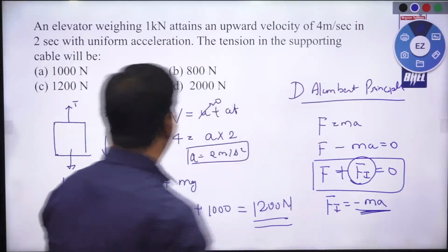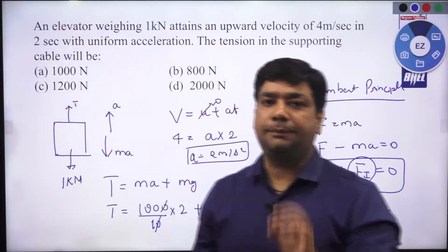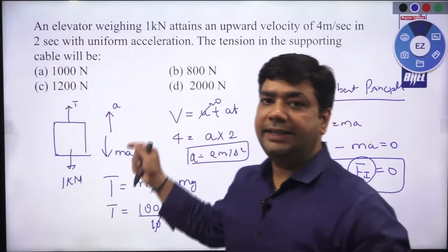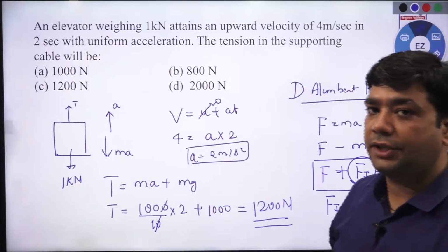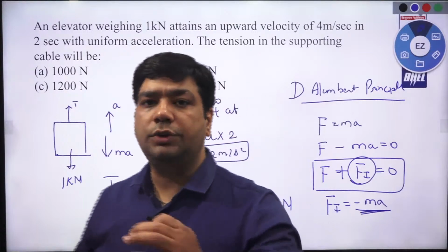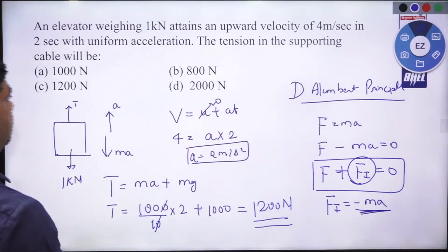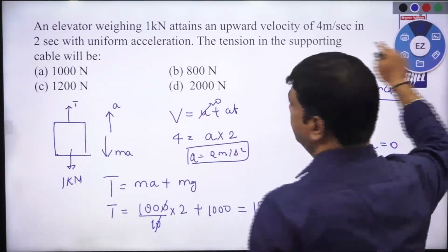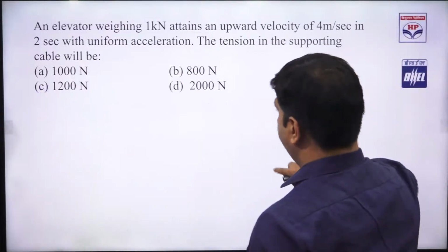So the moral of the question is that you understand what we mean by the D'Alembert principle. D'Alembert principle is nothing else, just introducing the inertia force, which has the opposite direction to the applied one, and equating to the equilibrium equation. Okay. Now just switch to the next question. So the answer is C.